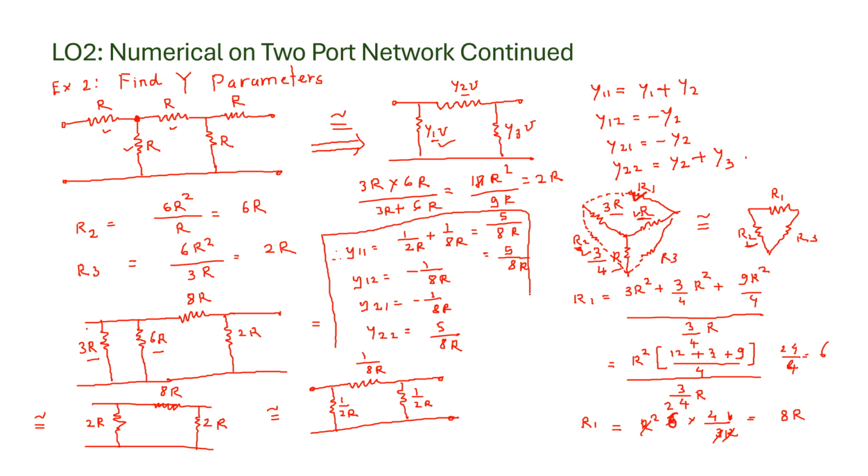Now I have not written any KVL and KCL equations. Simply I have used a series of star delta conversions, and we were able to find the Y parameters for this circuit. Okay, so this is valid.